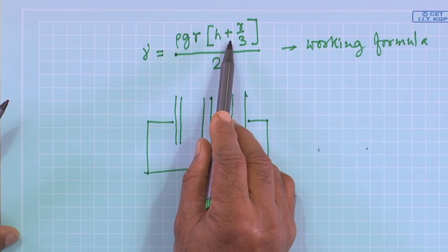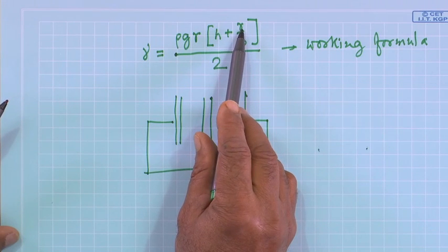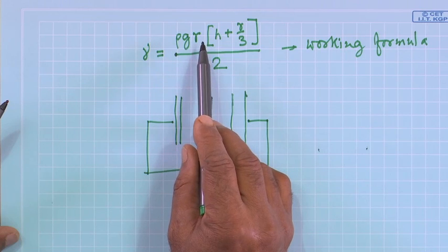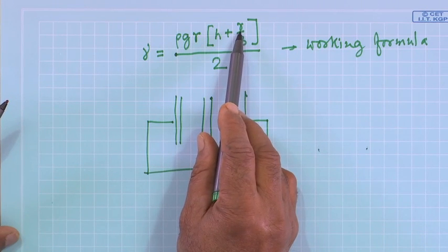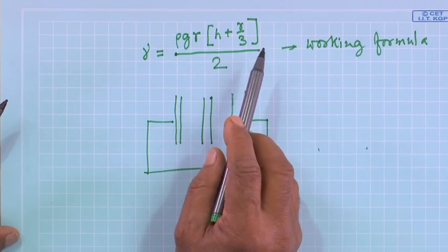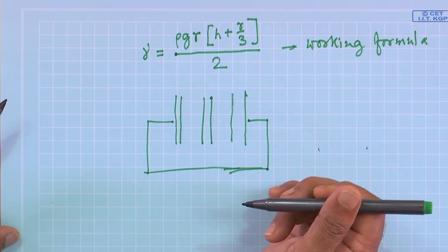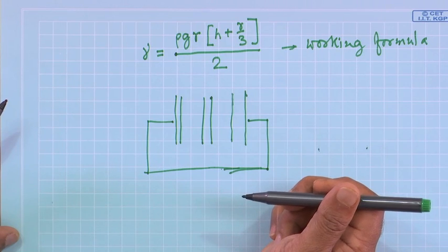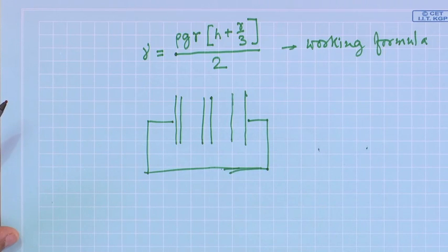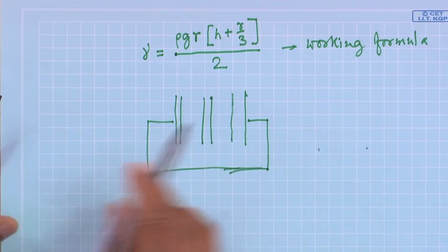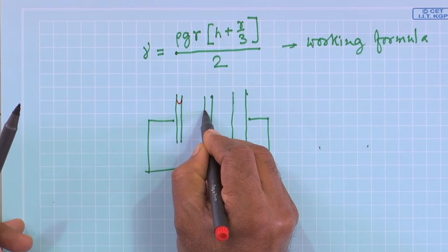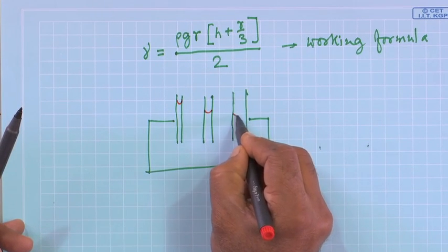So, here basically, depending on R, H will vary. In our hand only, for a particular liquid we can vary R, and for different R, H will be different. Okay. And so, this experiment will be repeated for different radius of the capillary tube. So, we will take 3 capillary tubes having different radius and do the experiment, and there you will see, as I mentioned, this kind of rise of the water.